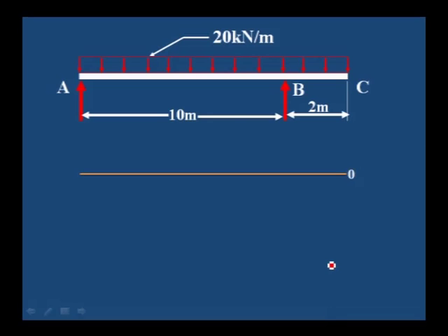Then this is the point where the total load is 144, out of which 104 is the negative value and positive is 40. You have to show the drop equivalent to the 144, and the negative shear force that we have calculated is 104. And here 96 is the shear force at A. Now you have to join this.